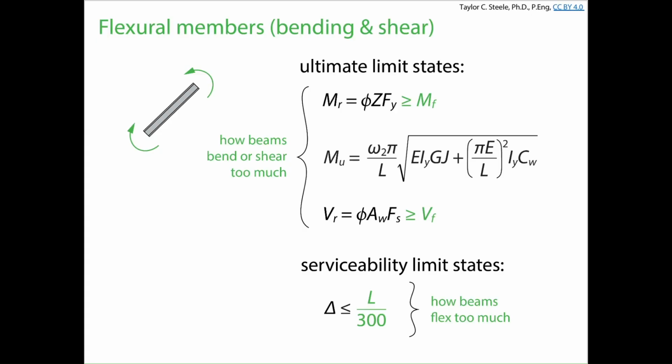And almost all the time, omega 2 is going to be a little bit bigger than 1. We're going to see for the most part, practically speaking, it's conservative to just take omega 2 as equal to 1. And for most of the girders in your example buildings that you're doing your design project based on, you're basically going to end up using omega 2 as 1 anyway, and we'll talk about why that is.